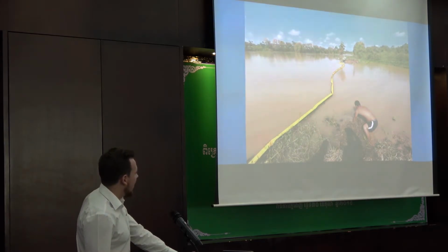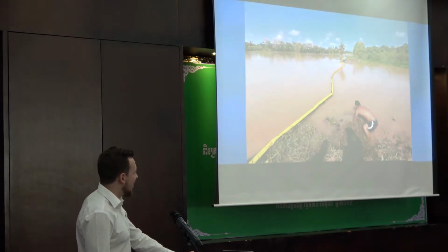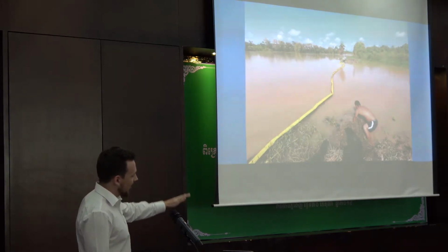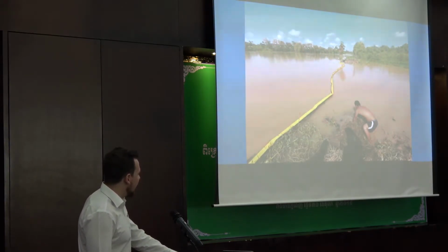It's important, we also have to make sure that we allow enough slack on the land anchor points. With a 2 metre change in river height, you need to make sure that the curtain can rise and fall with a change of conditions. So we allowed the extra slack with chains connecting the curtain to the land anchors. We didn't attach the curtain direct to the anchors.